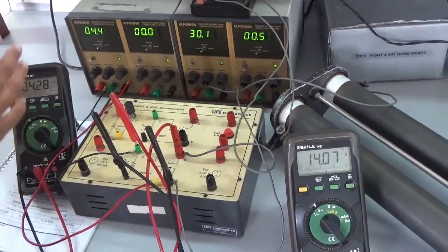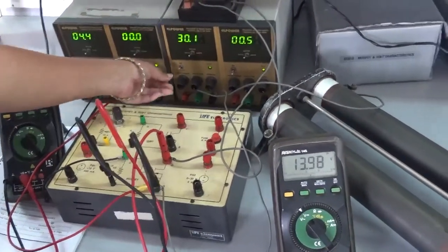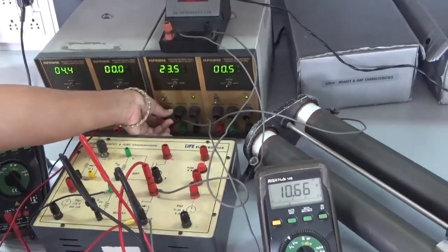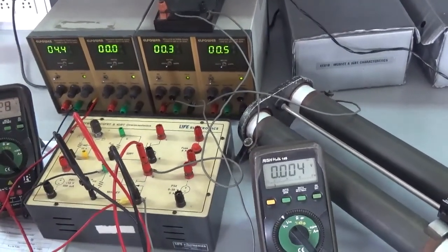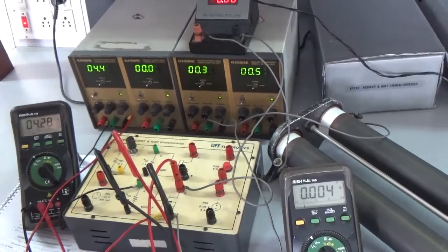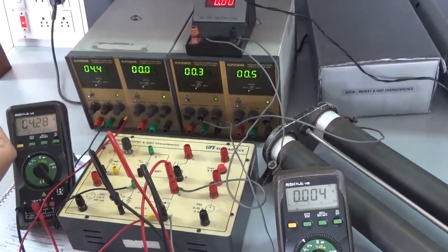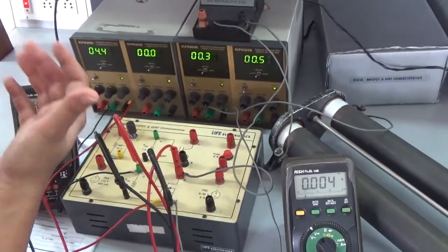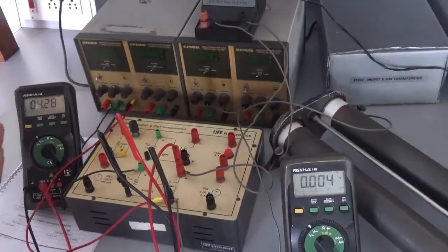Now we should not disturb this gate side part. Leave it as it is and reduce VDD to 0. What we did in this process is, we had set the value of VGS. When we give VGS any value like 2 or 5 or 6, the Q point may result either in cutoff or saturation. We don't want the Q point to be set in cutoff or saturation. We need it to be in the active region.